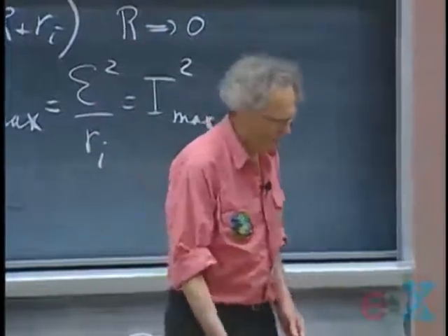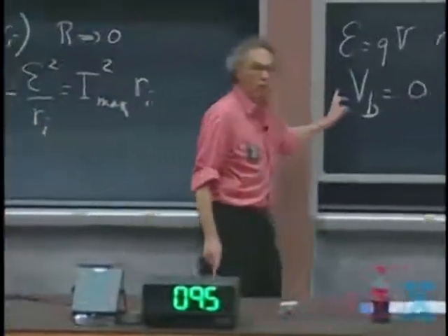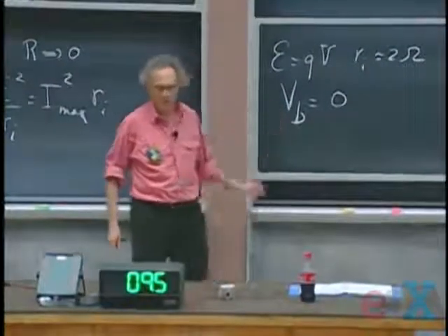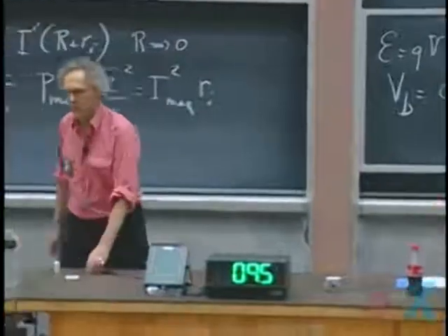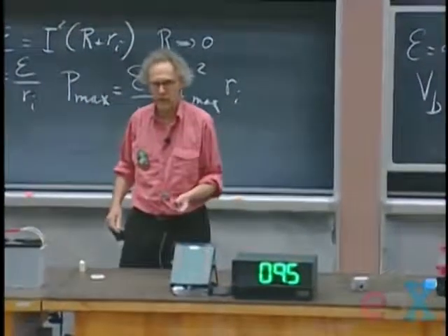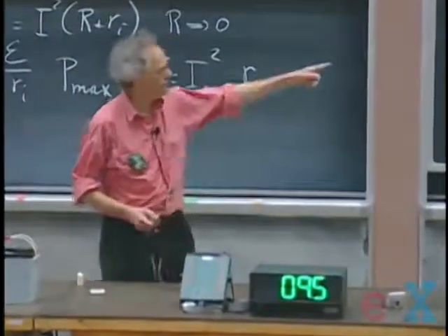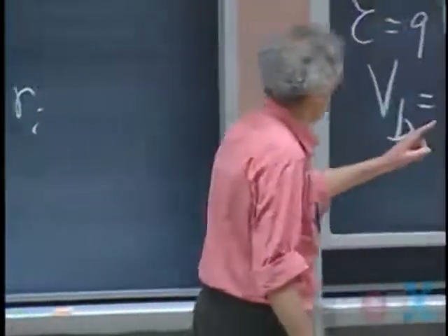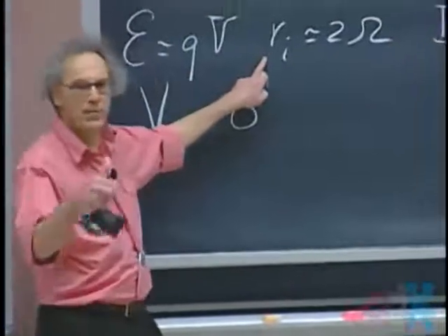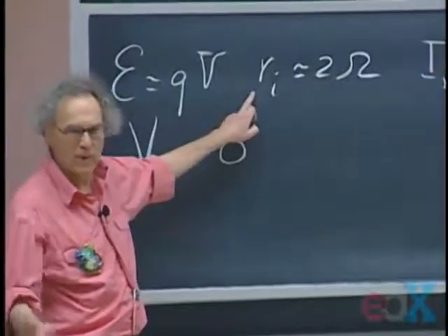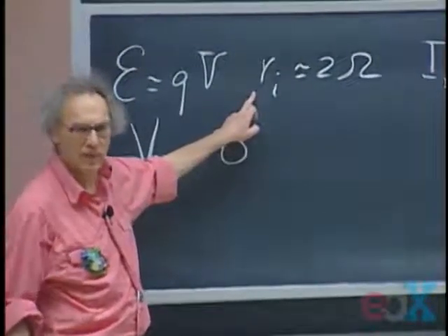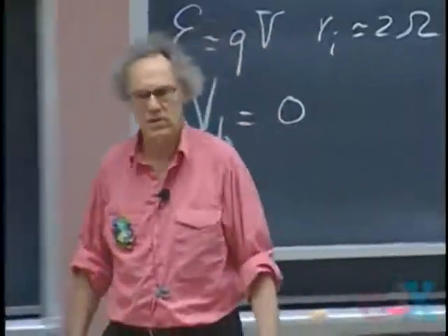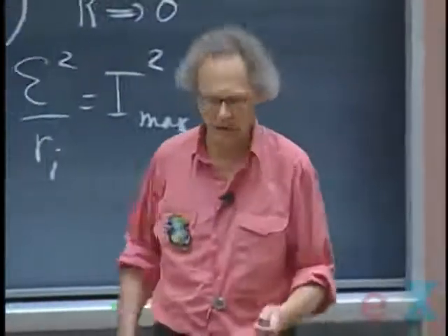And so the voltage that you're going to see is maybe not going to 0 exactly, because my key may not have 0 resistance, but it goes very low. And what you cannot experience is something that I can, that this battery will get hot. This 40 watts will be generated inside here. It is possible, though, that when the battery gets hot, the internal resistance may even go up a little, because remember that resistance goes up when temperature goes up, in which case the power will go down, so it may not be the full 40 watts. But I can assure you that I can feel this thing getting warm.